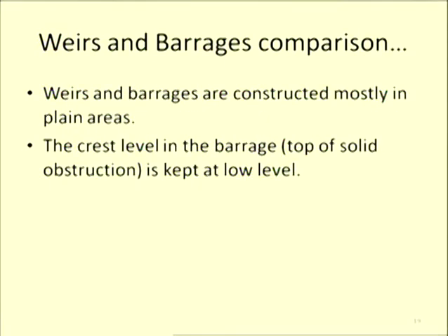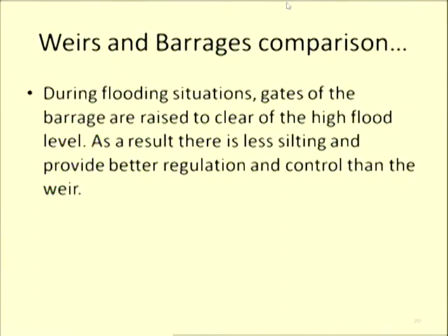Weirs and barrages are constructed mostly in plain areas. The crest level in the barrage, the top of the solid obstruction, is kept at a low level. It's not that high, only a few meters, meaning only 2-3 meters or 4 or 5 meters. Beyond that, the height of the reservoir is created by closing the gates. So that is the basic comparison of weir and barrages.